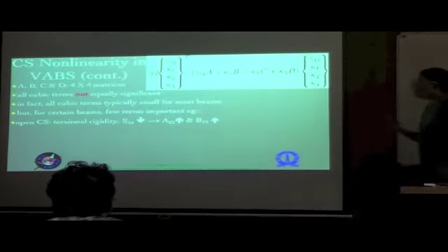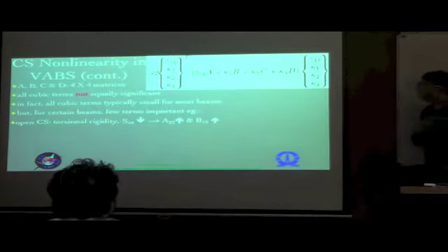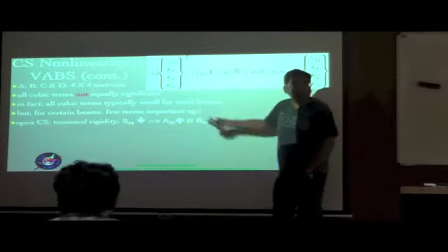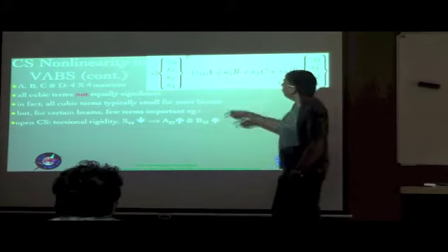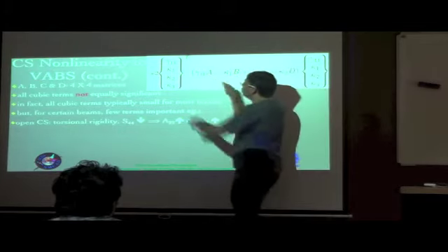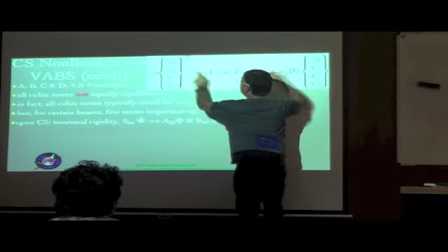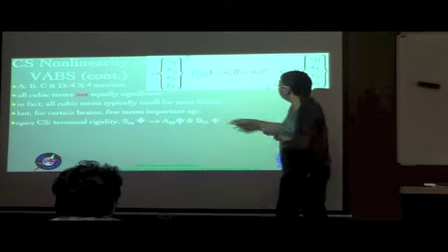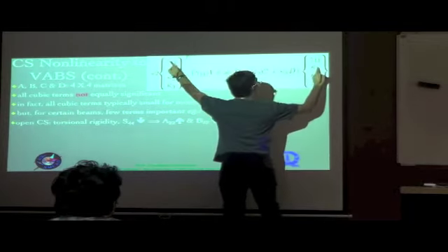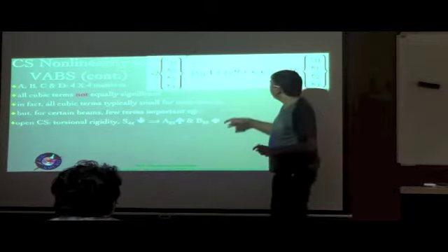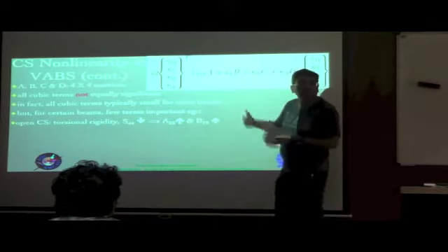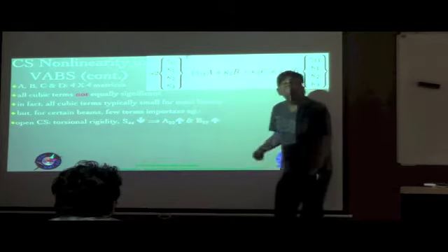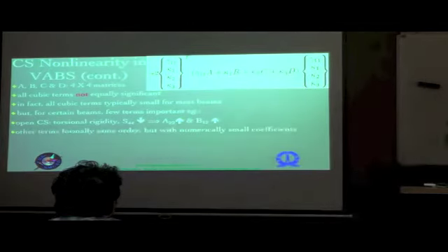So the torsional rigidity for open cross sections is small, and so in other words, S44 is small. In other words, the nonlinearity associated with kappa 1 become important. A22, for example, is the 2 term, so it multiplies kappa 1 squared with gamma 1 1. So it's an extension twist kind of a coupling. Again, B12, if you look at the 1 2 term is gamma 1 1 kappa 1, and that's multiplied by kappa 1. So again, it's a gamma 1 1 kappa 1 squared kind of a term. So those would be typically large for most open cross sections.